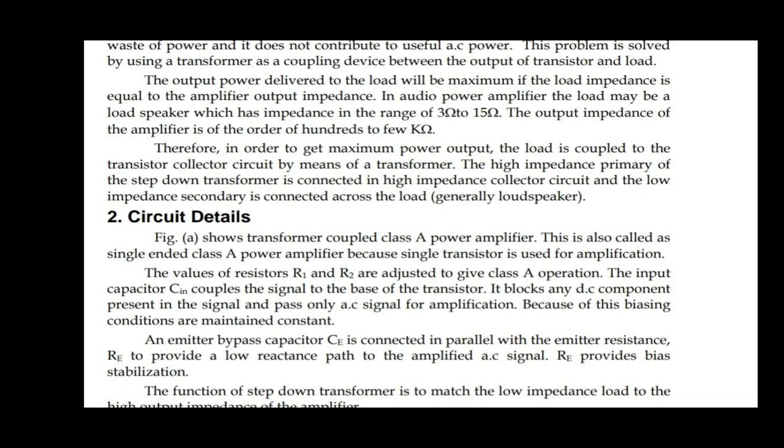Therefore, in order to get maximum power output, the load is coupled to the transistor collector circuit by means of a transformer. The high impedance primary of a step down transformer is connected in the high impedance collector circuit, and a low impedance secondary is connected across the load, generally a loudspeaker.